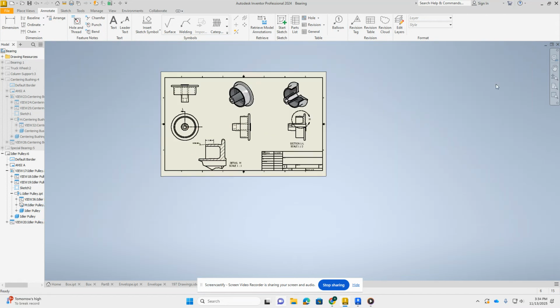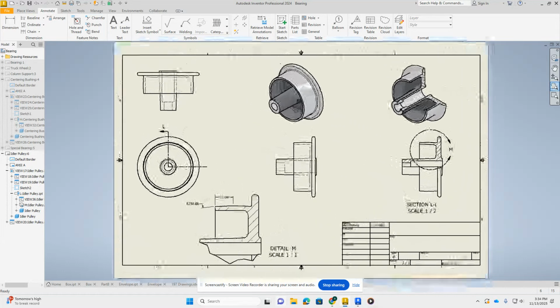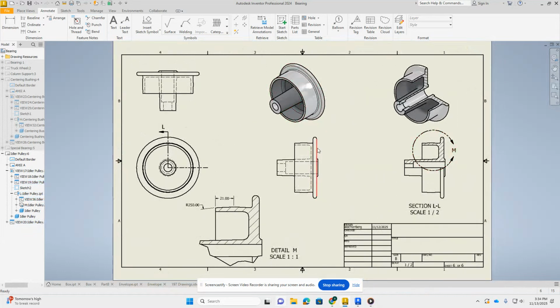From there, you have all of your other dimensions on the PDF. You can start dimensioning this. Pick the best spots where you can see stuff. You may end up putting quite a few dimensions over here. You may not. It is all entirely kind of up to you. Do not dimension to hidden lines if you can. There is one hole through here, so you do have to point at that one. But that is it for this video.